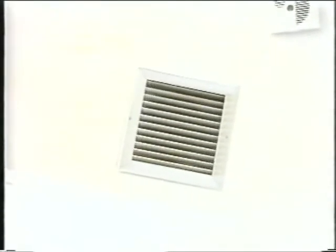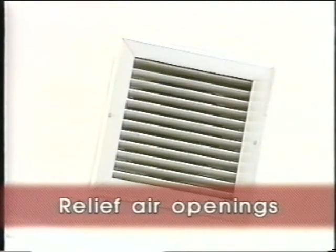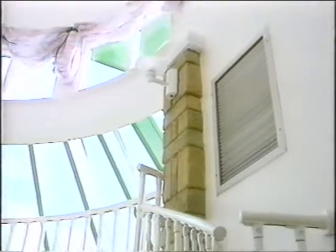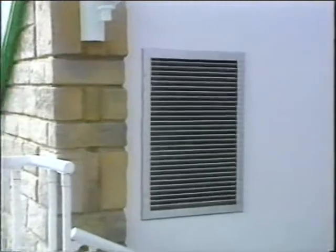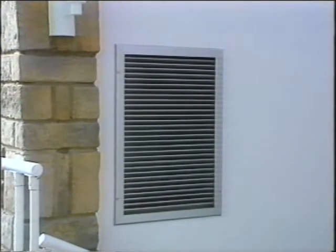The air that's displaced by the warm air as it's blown into the various spaces returns to the heater through grills like these, known as relief air openings. It returns from all heated rooms except the kitchen, bathroom, WC and shower. Just like warm air ducts and registers, return ducts and grills and relief openings need to be properly sized. Once again, there are tables to help you with your calculations.